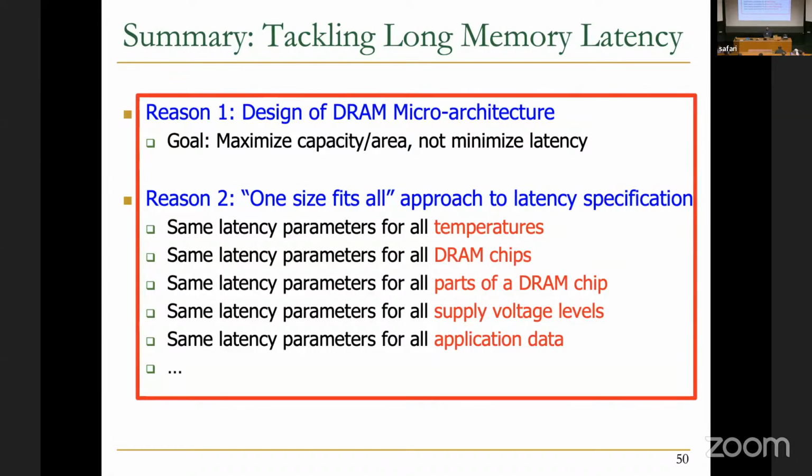I mentioned the tiered latency DRAM work. The idea over there is, as opposed to having bit lines that are long, to segment the bit lines, meaning divide the bit lines into 2 portions, isolate one from the other, and part of the array can be used as a fast cache. And this is one of the initial works. There are also later works that improve upon this idea. But I would recommend people to think about that direction as well. Basically, today's DRAM is not designed for low latency, nor is it designed for computing inside memory. So when you're doing computation near or inside DRAM, you're working against both of these currents. So it's good to think about that.